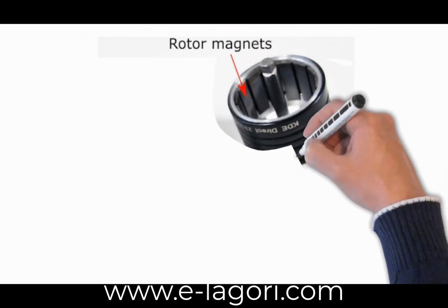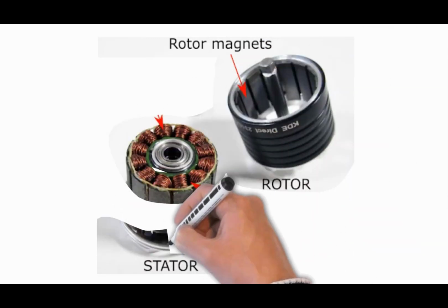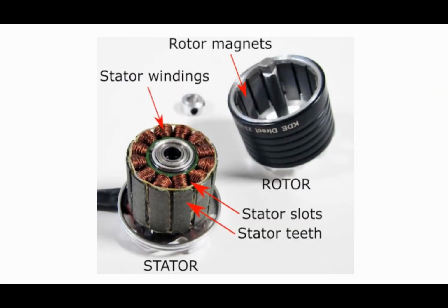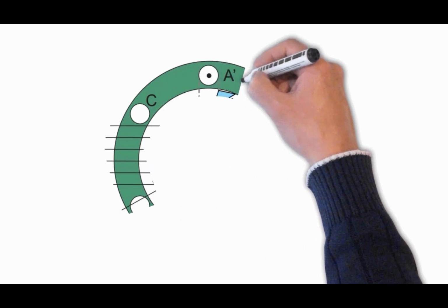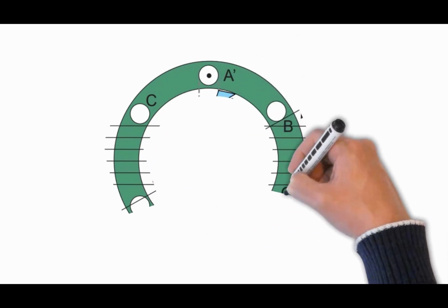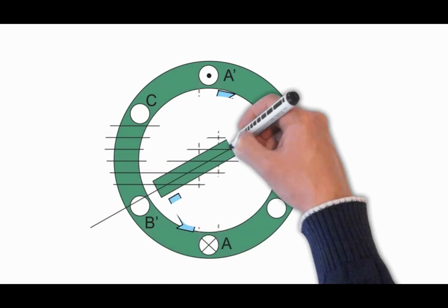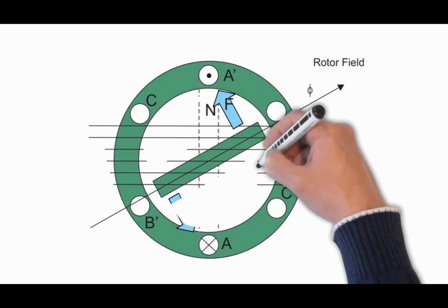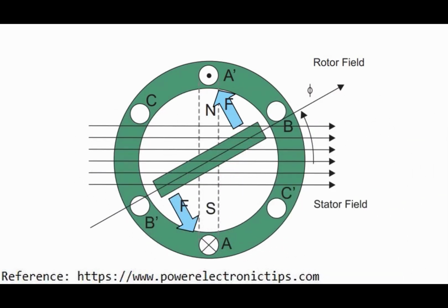The brushless DC motor, aka BLDC, has a rotor which is a permanent magnet, whereas in brushed DC we have a permanent magnet as a stator. Here we achieve continuous rotation, or a rotating magnetic field, through regularly switching current in the stator with only two poles active at a time. Since you don't have parts in contact, BLDC lasts longer with less wear and tear. Also, BLDC motors are way more efficient.